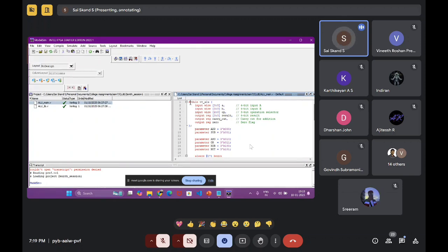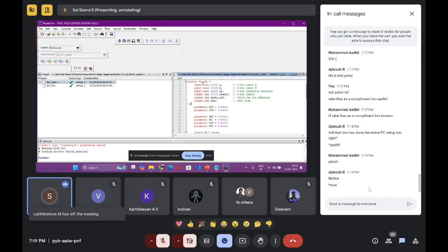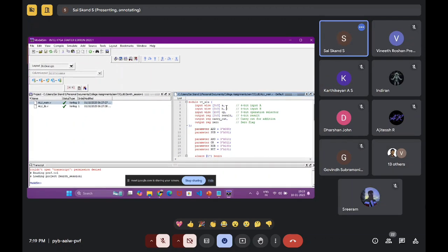It's basically module based. This module is basically like a function, it defines the functionality to be implemented. This is the main code, the basic idea of an ALU, a very simple one. We are going to do a 4-bit ALU. It's going to perform 4-bit operations between 4-bit data.